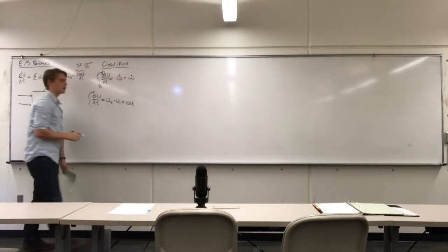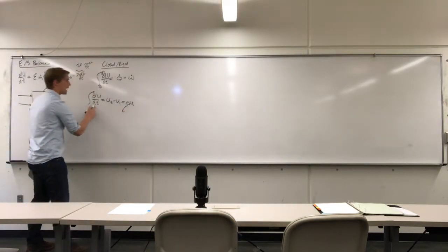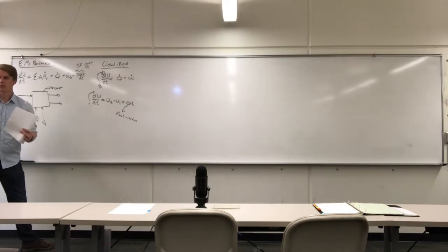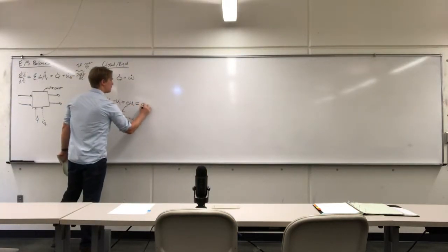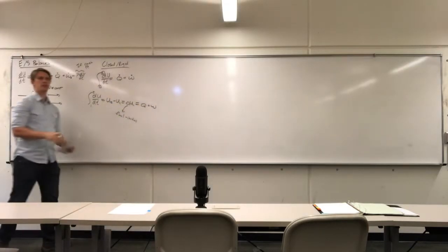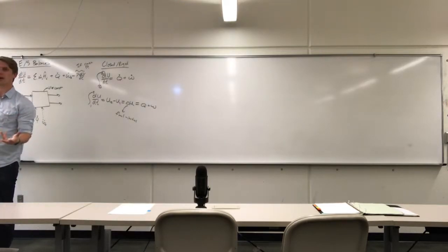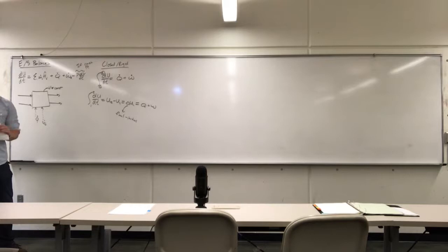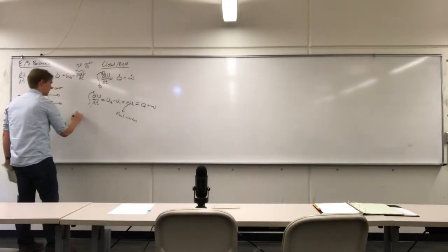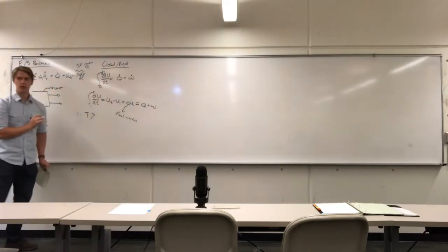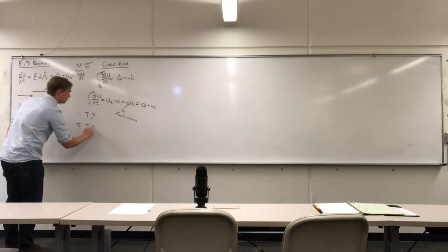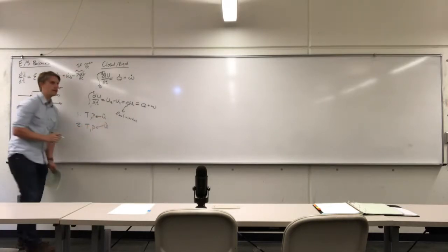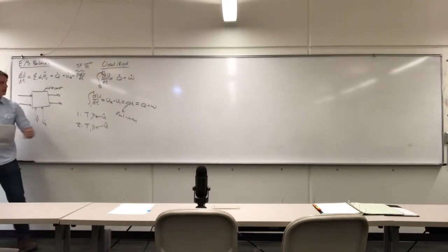This is also equal to what we call delta U. In this case, we can think of this as final minus initial. This is what the delta represents. This hopefully shouldn't be shockingly new nomenclature. And in this case, we notice there's no dots here. That's because it's not the rate of energy in the form of heat or work, but the total amount of energy in. So if we were given a piston cylinder problem with water and you had the steam tables, all we would need to do is note that state 1 would be at some temperature and pressure condition, and state 2 would be at some temperature and pressure condition. All you would do is go to the steam tables, look up what the internal energy of water was at that condition, and plug it into this equation.